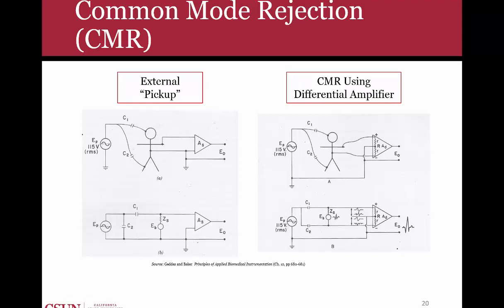And for those of you that have ever designed an ECG or anything like that, or just played with some of the SparkFun electrodes that you're given, you'll notice that you have a 60 hertz noise always impinging on your signal, and that 60 hertz noise comes from the walls and any other equipment that you're standing near.